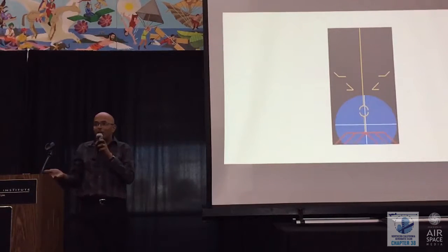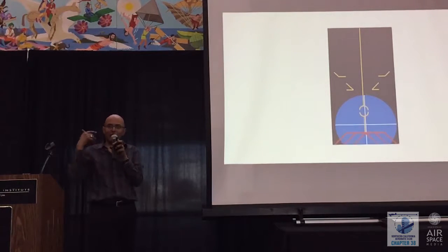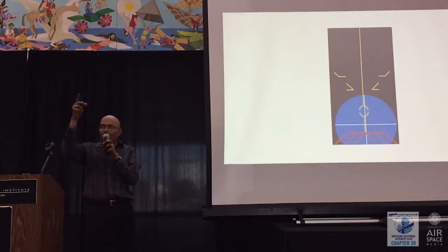And the important thing to keep in mind here is every one of these things I've shown you is like a snapshot of a certain flight condition. And you can remember this right away and be able to just recognize it when you see it. Just at a glance, you can look at it and say, that's where I'm going. And that's much better than having to see these two or three or four different instruments all over your panel that you have to chase around.